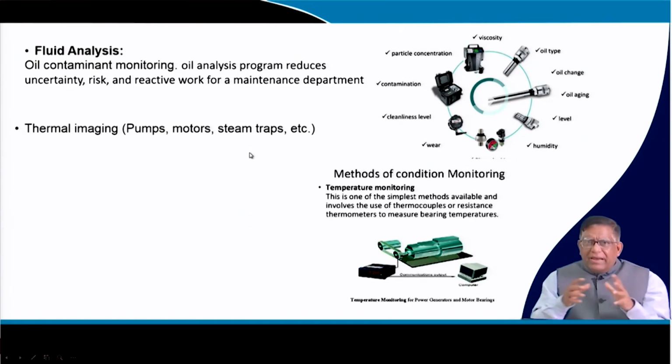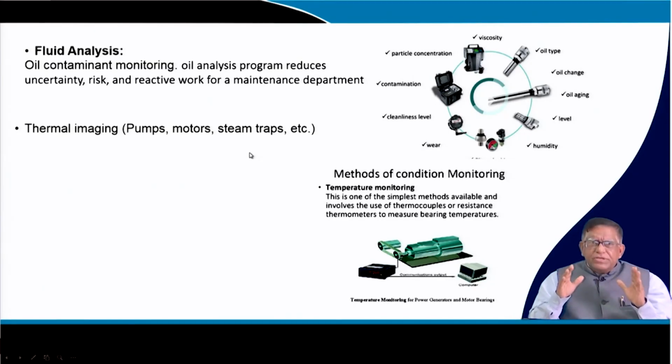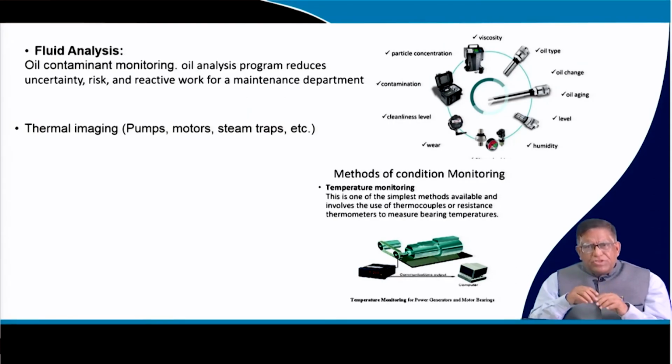Then there is thermal analysis, in which they monitor the temperature in a particular pump, motor, or your steam traps, etc. in different processing plants and power plants. The temperature mainly rises in the bearing portions if lubrication is not done properly. If the temperature goes high, you keep on monitoring it and then you can act.